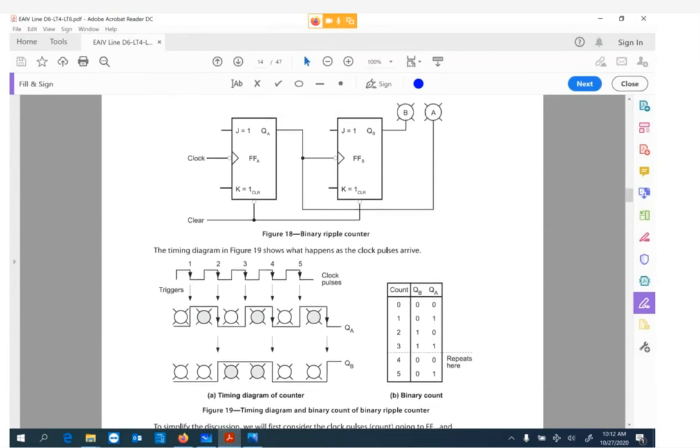Right, so we get our trigger pulse. As long as we have J set to 1, right, it will count to 1 here. The next pulse, trailing edge, counts to 2. Next pulse, 1 and 2 are on, which counts to 3. The next pulse, right, it resets. And then it starts over. So we only can count to 3 in this case.